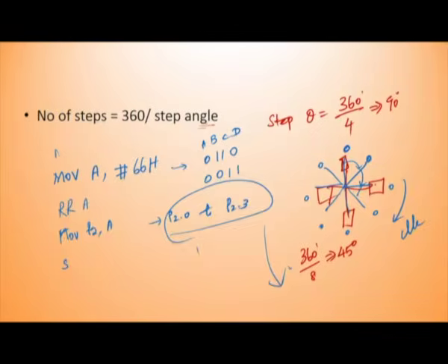Suppose you want to give only 10 steps or 40 steps, here you can give MOV R0, 30H. If you know the counts, you give it, and here you can use DJNZ R0 to jump back to the loop. This kind of rotation you can also perform, and at the end you can finish or use a short jump. So, initialize the starting value, then start the rotation.